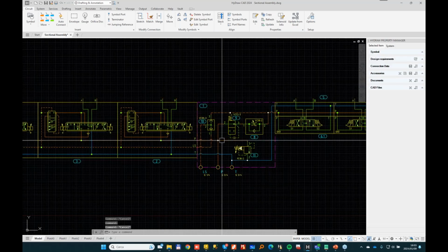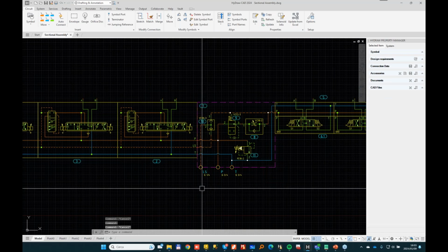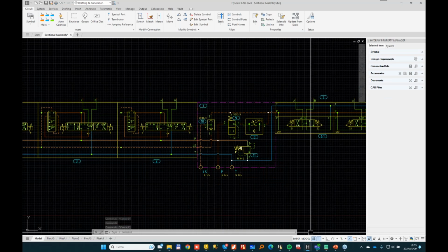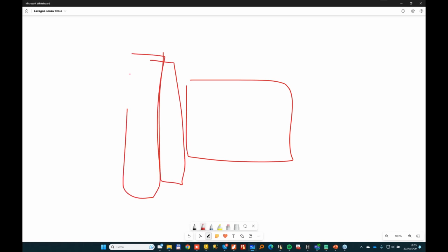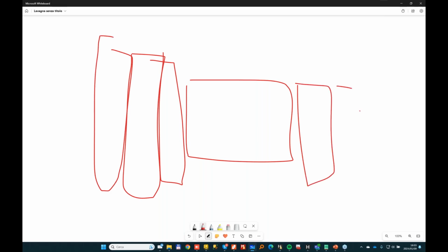So my mid inlet will be the following. In terms of design structure, basically I'll draw my manifold in between. I will have my working section on the left for the Bosch Rexroth elements, and on the right I will have the Eurofluid subplates. My P and T will be here on the front face, and then I'll put valves on the top face.